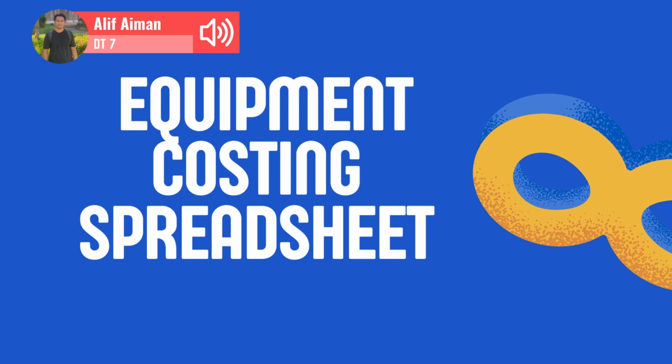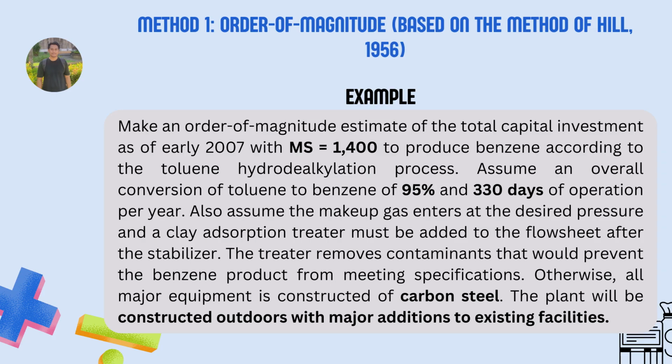So next, let's continue with the equipment costing spreadsheet, where we use Excel to calculate the equipment cost. So for the first method, let's try this example from the book to solve by using the Excel that we already created. And from this example, we need to highlight the MS cost index, the conversion of toluene to benzene, and also the operation time to calculate the production rate of the benzene. And we need to highlight the material of the major equipment like carbon steel, and also the condition of the plant that is constructed outdoors with major additions to existing facilities.